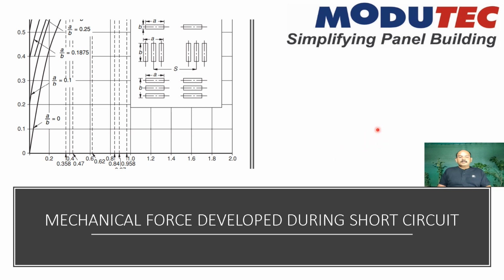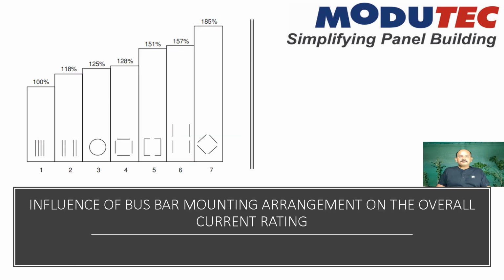So, mechanical force developed during short circuit. This is the center of bus bar A and here the center of bus bar B. This is S, the distance we need to maintain. Based on our short circuit levels, we can maintain this distance. Based on our bus bar arrangements, the current carrying capacity we can also improve using the same bus bars.